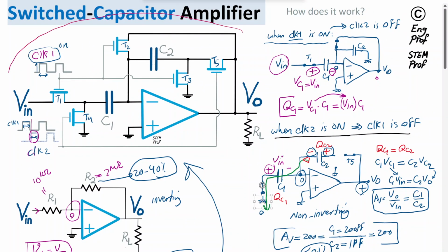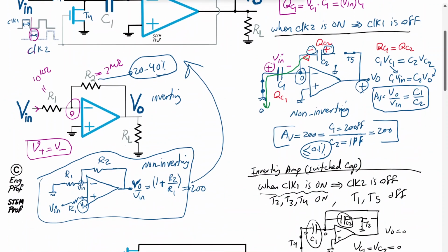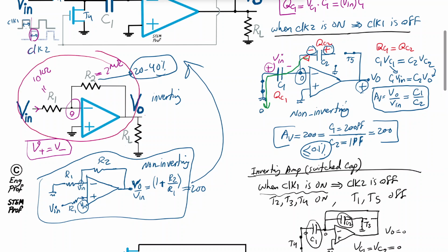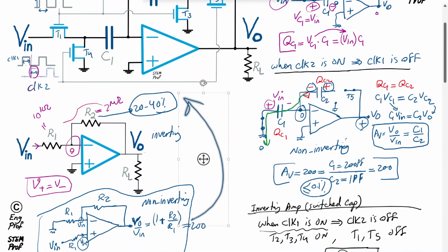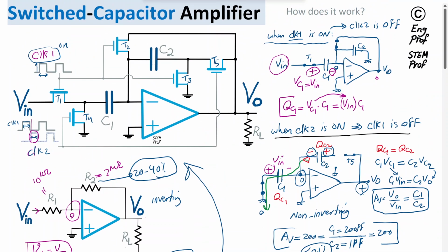The actual size, or silicon footprint, as they say, that this circuit occupies on a chip would be much smaller than if somebody wanted to do it with 10 kilo ohm and 2 mega ohm passive resistors, which would have huge silicon footprint, which is pretty expensive and also inaccurate, with lots of parasitic effects associated with the caps, equivalent cap that is coming with resistors, and other variations as well. So a lot of non-idealities.